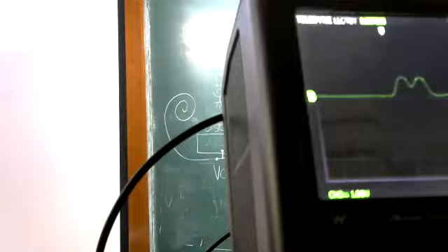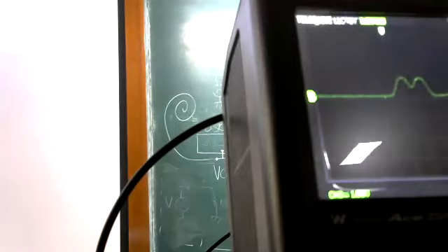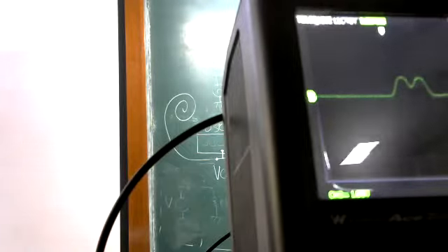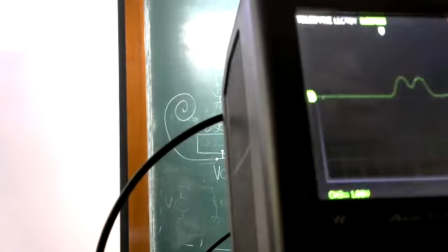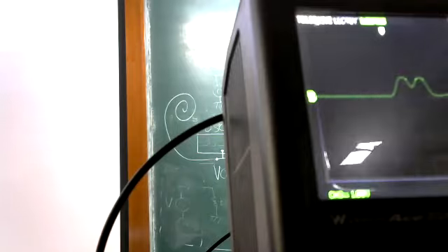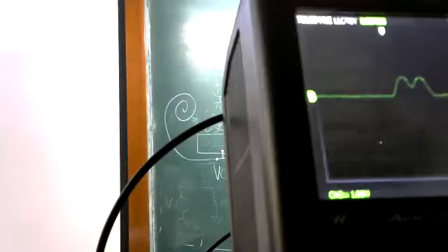But this entire experiment is limited in frequency anyway, because this guy cannot create frequencies beyond 30 megahertz. This cannot measure frequencies beyond 100 megahertz. So it works as a reasonable short circuit. And especially for the phase, the fact that it's flipping the phase, that will always work as long as the impedance is below some value. So you will see the effect very clearly, as we can see here. Okay. That was the last thing I was going to do.